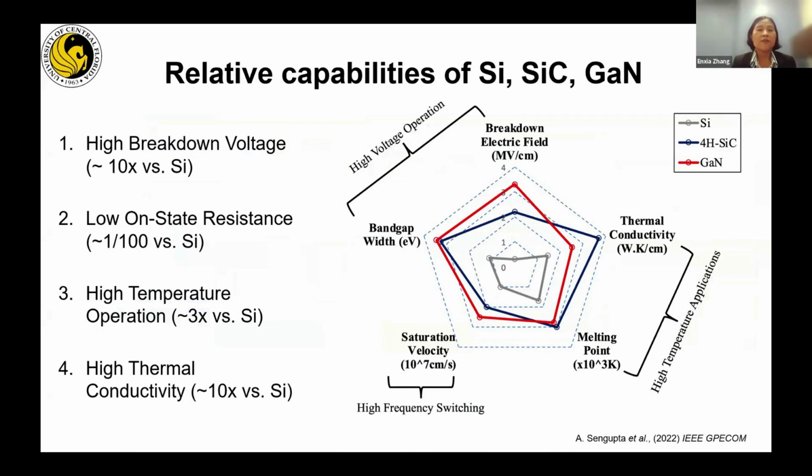This talk's main focus is on silicon carbide, compared with other wide bandgap materials. We can see the wide bandgap compared with the classical silicon-based devices. You have high breakdown voltage, low on-resistance, high temperature capability and high thermal conductivity. Those are very good for space and power systems.